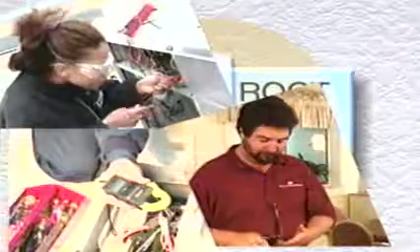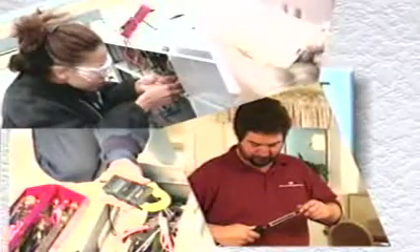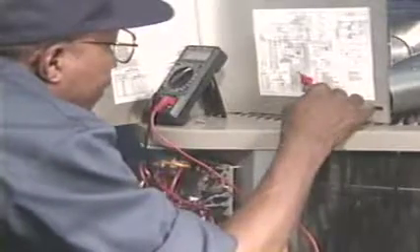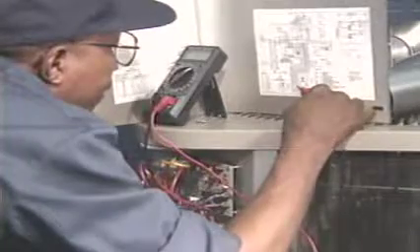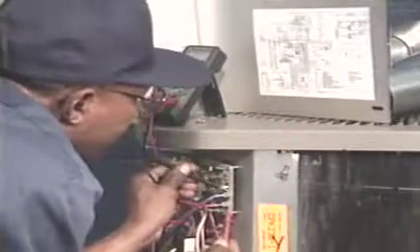Isolating the problem is a logical, step-by-step process of elimination using test equipment. It starts with knowledge of the specific equipment or component being tested. Different makes and models of HVAC equipment operate on the same basic principles and have the same types of systems. So, even if you're dealing with a make and model of equipment you've never seen before, the schematic plus your general knowledge of HVAC systems will often be enough to help you solve a problem.